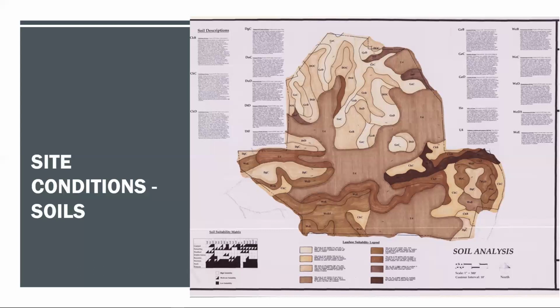Depending on the site's location and intended land use program, an inventory of soils may include attributes such as acidity or alkalinity, pH levels, soil permeability, any erosion potentials, depth to seasonally high water table, and of course, depth to bedrock.